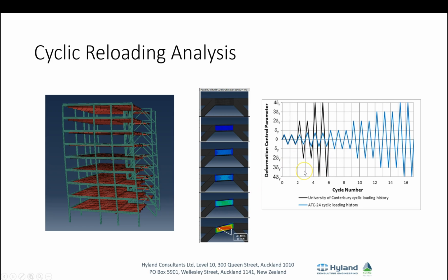So the results were quite interesting. It showed us that we had plenty of capacity remaining in those links, and in fact the second reload of these, when we broke the material properties up into 4 subsections within each of the links, where we used the strain results from the first analysis to say this was the pre-strain level that it effectively got to, and then used steel properties starting with that level of pre-strain back in the model, so that we could see when we ran the second analysis whether it would survive or go worse.